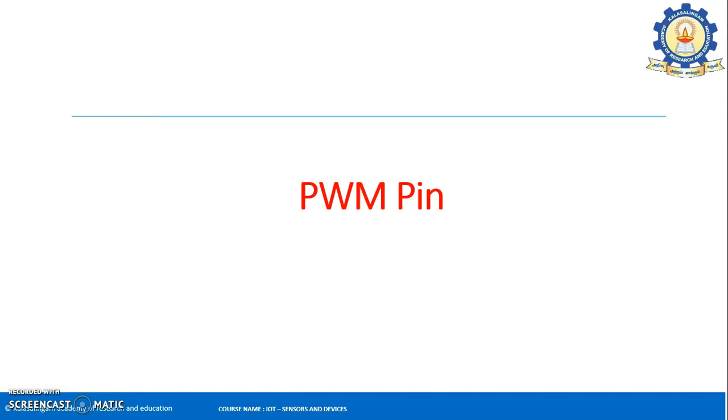What does this PWM stand for? It stands for pulse width modulation. Okay. So you know what a pulse is, and you're going to vary the width of the pulse using this pulse width modulation pin. The normal pulse width is like half. So the width will be on for half of the duration and off for half of the duration. That is what a normal pulse will look like.